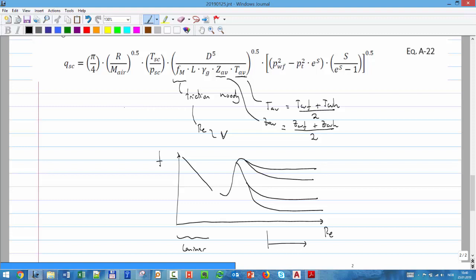What does it depend upon? The roughness of the pipe. If you see the cross-section of the pipe, you have some valleys; you measure that roughness, which is E, and then you make the relative roughness E by D. With gas, due to its very low viscosity and the high velocities it usually has, gas is almost always in that range.